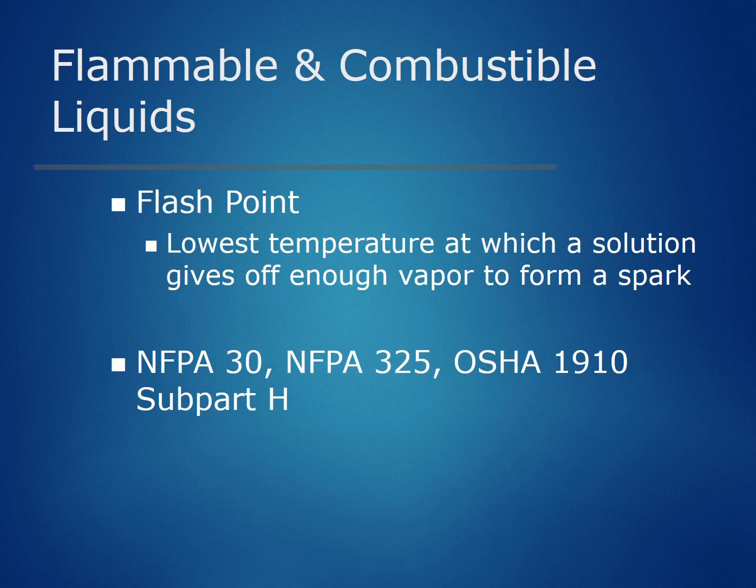That is, the lowest temperature at which a solution gives off enough vapor to support a fire. You can find lists and criteria regarding flash point in a number of regulations: NFPA 30, NFPA 325, and OSHA 1910 Subpart H.